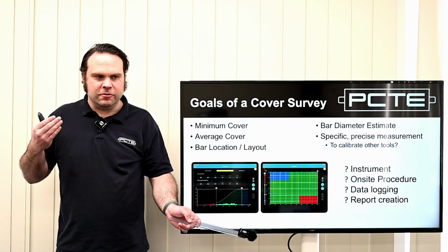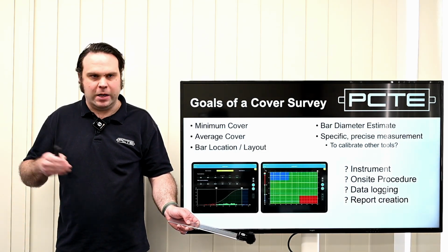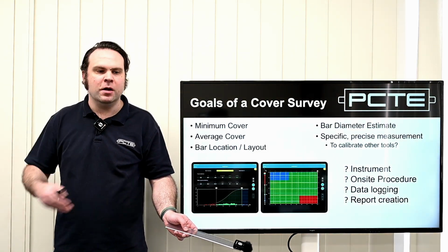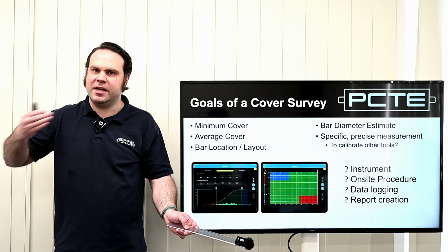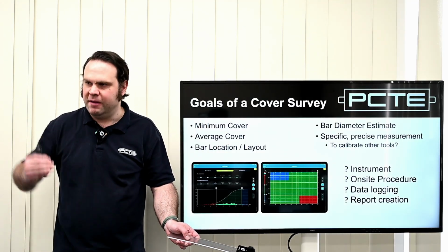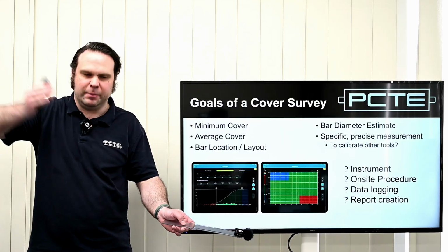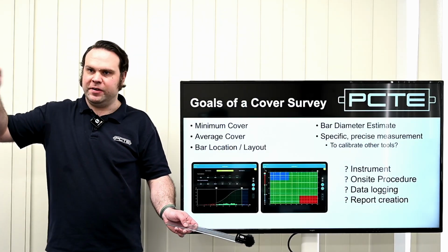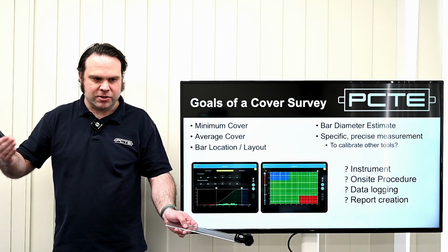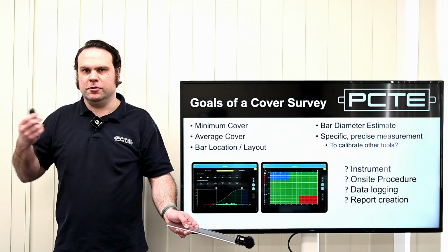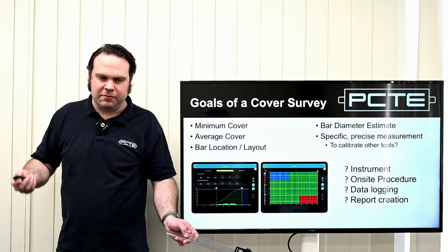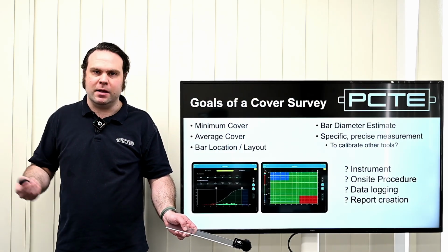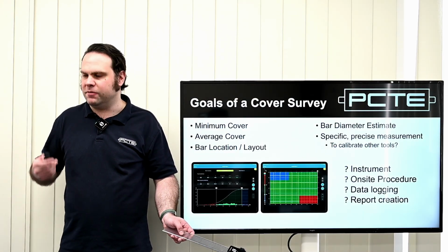A fairly straightforward application where we just maybe do some location work, or do we have to have an entire record on a precast element that's heavily reinforced telling us to check 50 millimeters in from one side, 30 millimeters in from other side, with a configuration that's proven to measure. And from that, we'll choose the kind of cover meter configuration we might use. We'll choose the documentation we'll use, maybe if we're going to set up the data logging functions in a device.